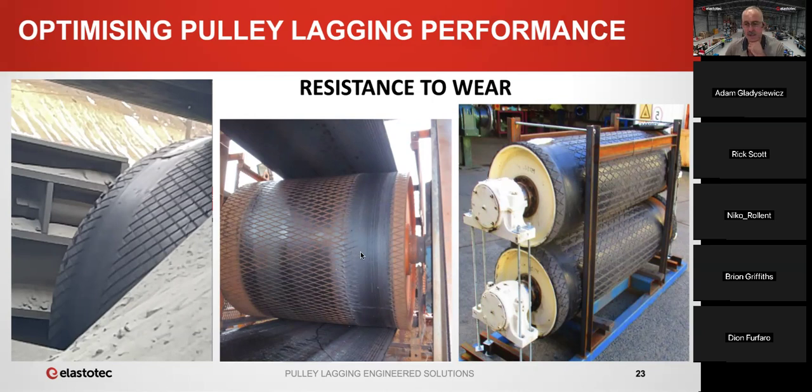That wear was occurring inside of 3 months and was causing serious problems. We changed that lagging to a polyurethane lagging, and basically that lagging lasted for 3 years. So we went from 3 months to 3 years by going to polyurethane.